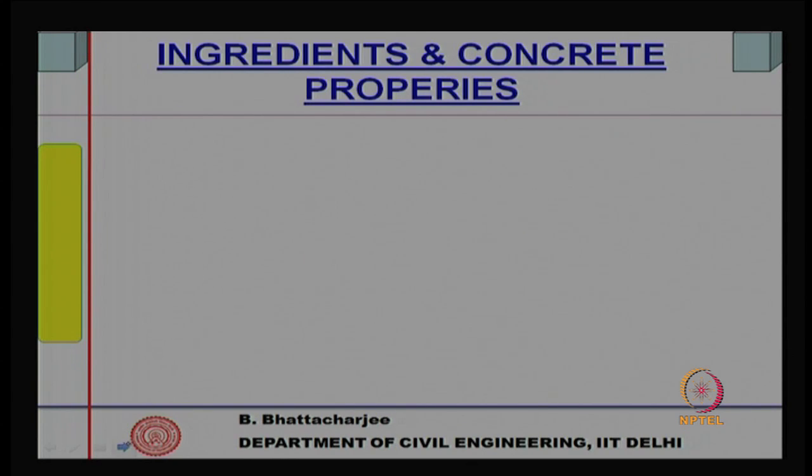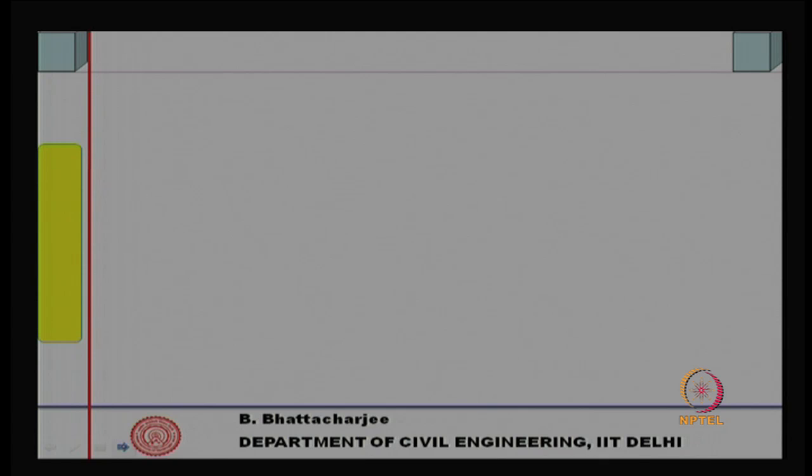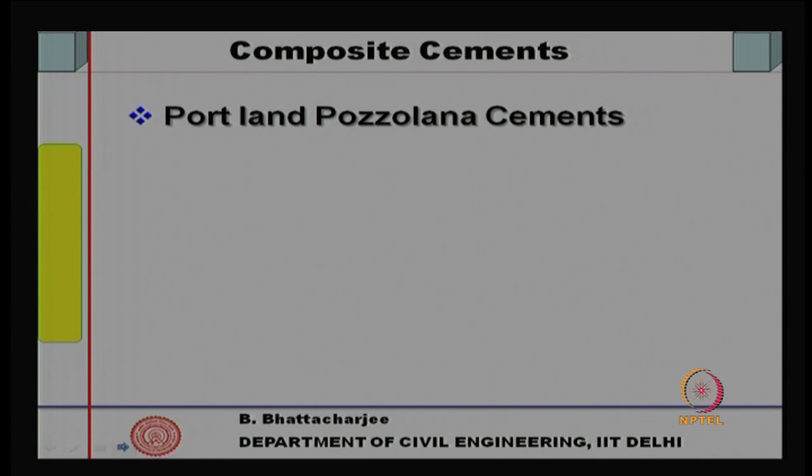So, blended cements are produced from this. One important issue is that when you produce such cements by intergrinding gypsum, clinker and the pozzolana, their initial strength is lower, but long term strength is better, particularly with fly ash. And so is the case with slag, but silica fume can show you high early strength as well. We will discuss this sometime later on.